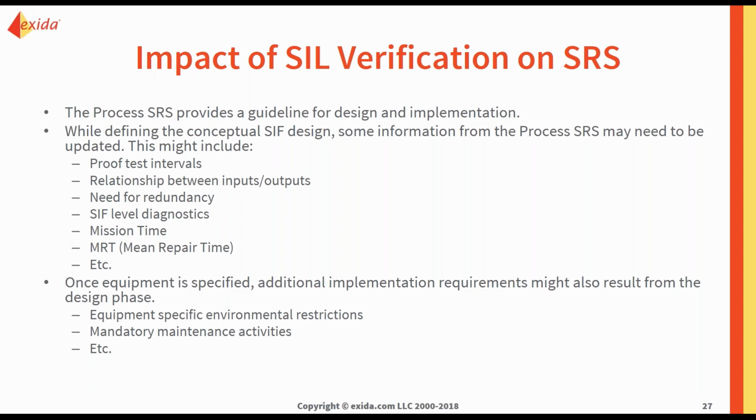Sometimes you think you're going to have a simple SIF and you go in and you're not reaching your target SIL level. So you might need to add some redundancy. You might need to add more proof tests, and so on and so forth. You get the idea. Any SIF level diagnostics, your mission time might change, your mean repair time might change. Once equipment is specified, you have basically set in stone your implementation requirements. So any equipment specific environmental restrictions, any mandatory maintenance activities can be specified here in the design phase.